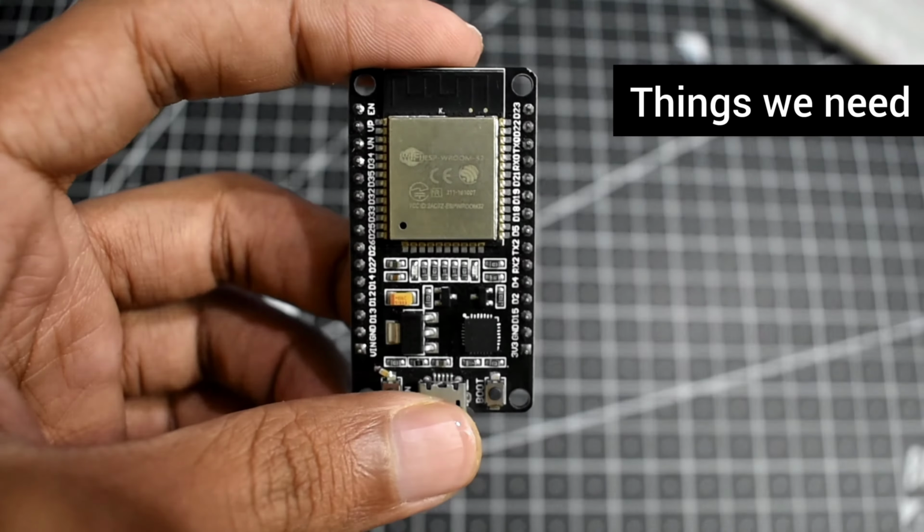So I'll write here Serial.print temperature, semicolon, Serial.print new line. And the variable name is a simple T. So paste it on a new line, println. Do the same thing with the humidity. I don't need this count variable.